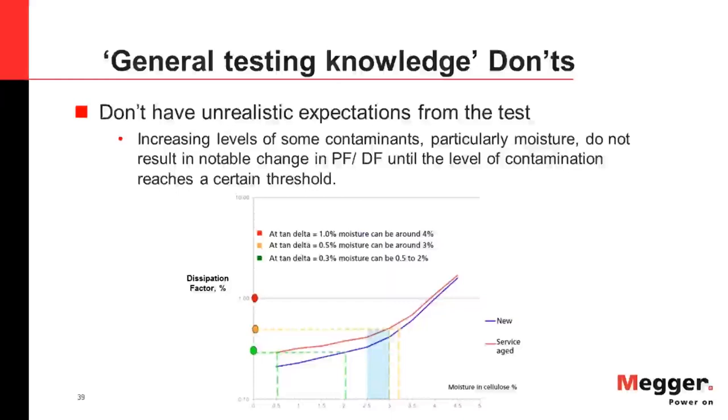So for perspective, operators become somewhat wary when percent water content exceeds, I don't know, maybe 1.7%. And by 2.5% water content in paper, they're typically scheduling a process unit to come dry the transformer.